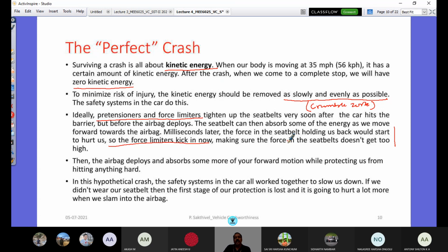What are the forces acting on different parts of the body, or the motion sensor or movement sensor showing the displacement of the chest, how much it has been compressed. That would all reflect whether these passive restraints are appropriately designed and act at the right time or not. That's why the full crash test with these restraints is conducted.